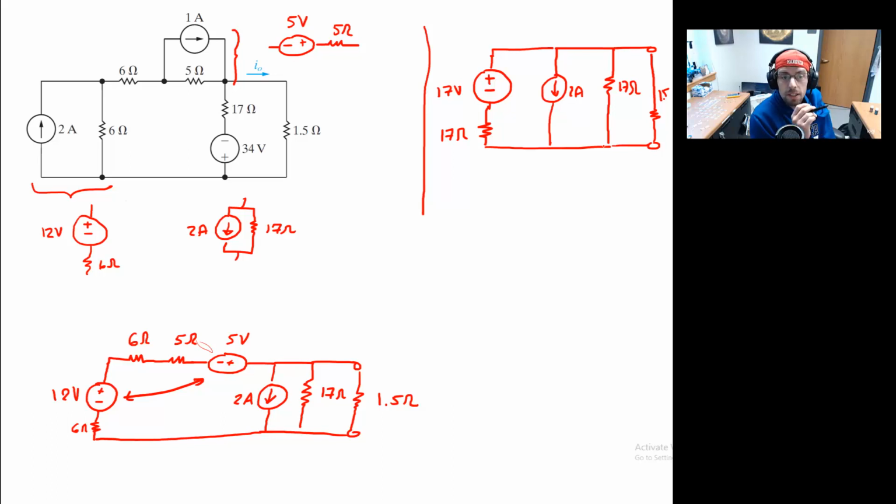Now you might be tempted to say, hey, why did I have to do this exchange in the first place, this current supply? Keep in mind that we would have had 2 different voltage supplies in parallel had I not done that switch. So we are going to need to exchange this left-hand side. We're going to have to turn that into a current supply. Then we can finally combine our current supplies in parallel, and then we can convert back if we need to. Actually, we won't. So this last source transformation is this left-hand side.